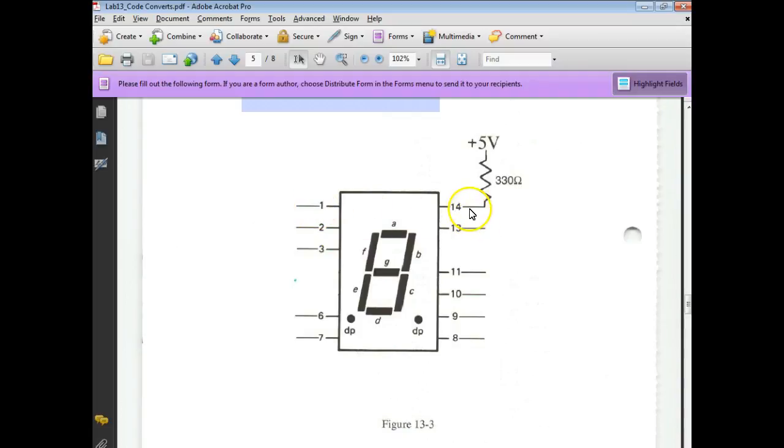So how would you find the power pins? You use your ohm meter. You put it on one pin, and you go down the ones on the other side. If you don't get continuity, then you move one pin over and go down the pins on the other side. You don't have to go down all the pins, just the other side, right? You understand what I'm saying?